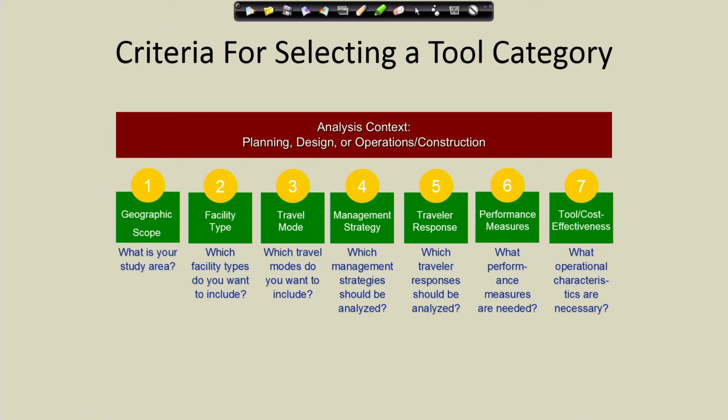Are you doing planning level? As I mentioned, when you do planning models, you typically use a macro level tool. European countries are adopting mesoscopic models for planning analysis. They realize it's important to model at least dynamic traffic assignment. Static assignment is so unrealistic that they switched to the meso level for planning. So it's changing over time, and computation power is supporting that kind of switch as well. At some point, we might be able to do a micro model for an entire city. That seems to be the trend.